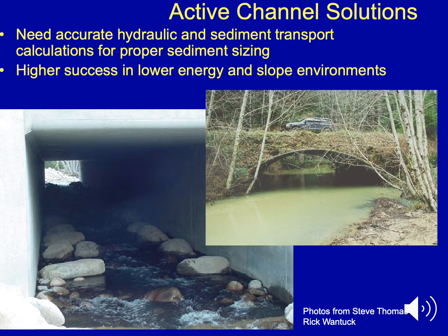Long term, it is very hard to keep the sediment inside a system where your width is less than the bankfull channel. To go back to that first slide I showed, where we talked about the fundamental tenets of fluvial morphology, a channel is shaped to transport the dominant flow and sediment load within its banks. Well, if you've narrowed that channel geometry, large flows tend to blow out the sediment that you're putting within your